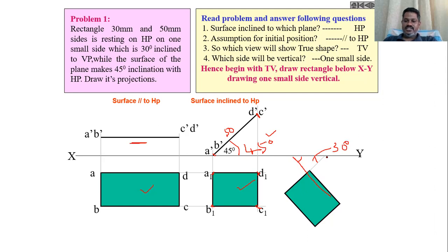With the 30 degrees, draw a reference line at 30 degrees angle. Then take the compass and name this point. Project all these points and construct exactly this shape at an angle of 30 degrees.